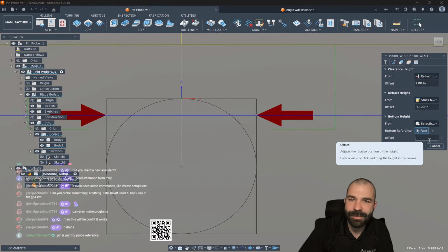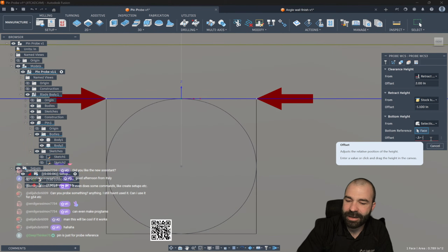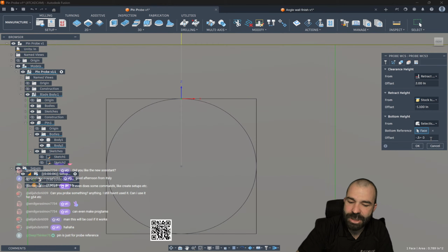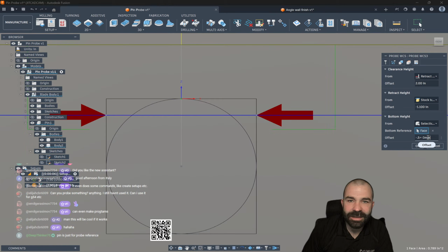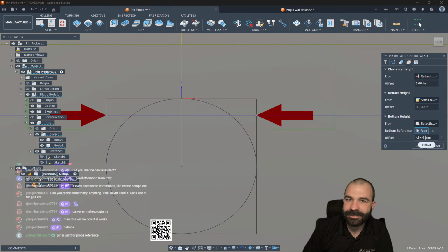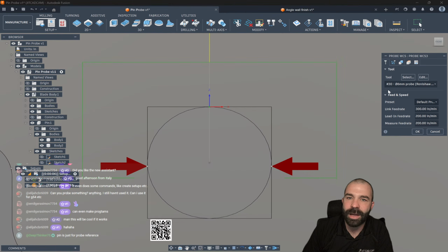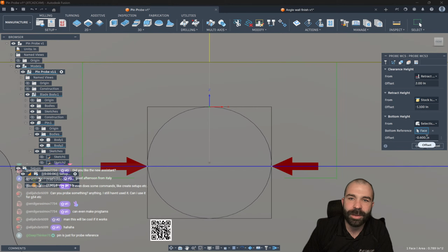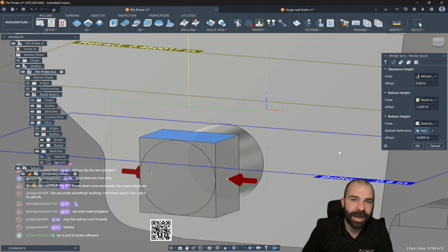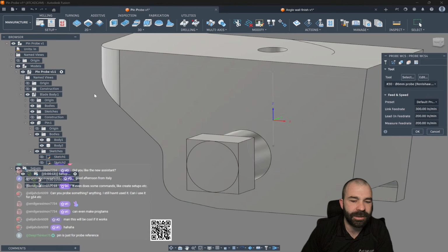Go ahead and redo my math here. We're going to offset minus 0.5 to get down, and then we're going to add another minus 3 millimeters, is it? Doesn't like both. Can you imagine that? Probably because I'm in this live meeting right now, like always, trying to do one or the other. But I think you guys are kind of seeing here. We're going to go ahead and guesstimate at 0.6. Call it a day. But the goal is just that. To be able to drop that down. Again, what I'm trying to do is that's a 6 millimeter probe. We should be able to drop by 3 millimeters more. But now you have your x-axis probing. And again, I could do another probe WCS here.